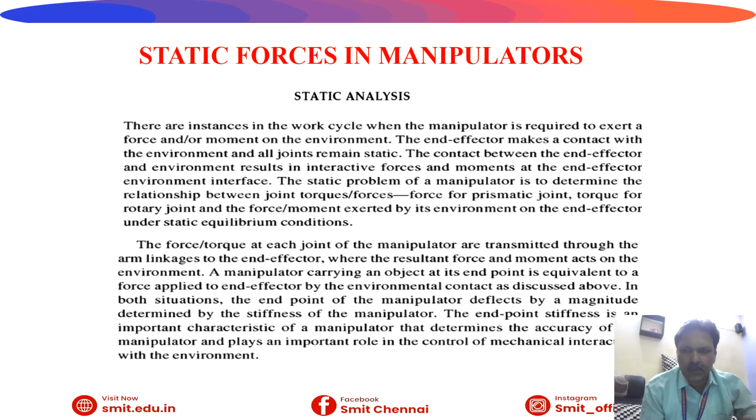We have already noticed in the engineering mechanics subject the various equilibrium conditions you might have studied. For the system to be in equilibrium, what conditions should be maintained and satisfied? Then the next one is the force and torque at each joint of the manipulator are transmitted through the arm linkages to the end effector, where the resultant force and the moment act on the environment. So whatever torque is applied at each joint of the manipulator is transmitted through the arm linkages to the end effector.